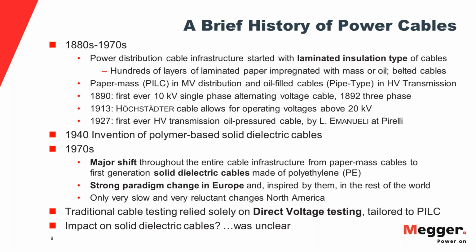And all the traditional methods, they were all tailored to these laminated cables. And now the question is, now we have all solid dielectric cables, XLPE, EPR. So what is this traditional testing doing on these cables? And that situation was unclear and got investigated and resolved over the years. So this is how it happened. So we went from paper mass and oil filled to XLPE mainly, and in North America a little bit EPR, because here EPR is for some reason more popular than in the rest of the world.